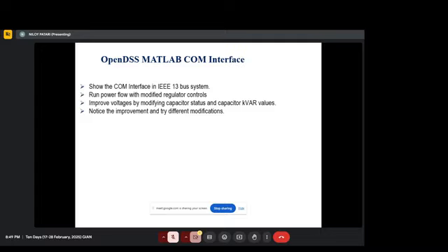Now, how do you know if these set points will solve your problem? Suppose initially in OpenDSS, when you run power flow, there is a voltage issue. You send all the voltage measurements to MATLAB. In MATLAB, the optimization problem gets solved, and then you send the set points back to OpenDSS. These set points are supposed to mitigate your voltage issues, right?